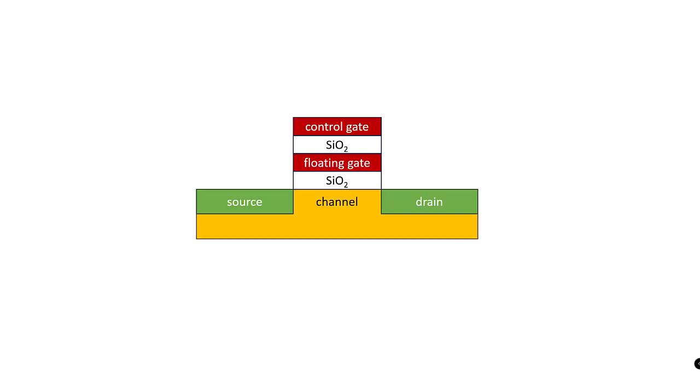Flash memory has become the predominant form of semiconductor storage of data for long periods without power. The basic architecture of the flash storage device is similar to that of dynamic RAM, but it makes use of different devices and circuits. A floating gate transistor includes 2 gates. The upper control gate takes advantage of quantum mechanics to write a value into the floating gate. The floating gate then controls the channel and whether it conducts.